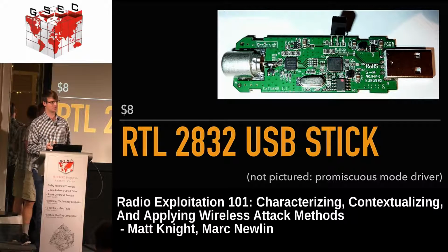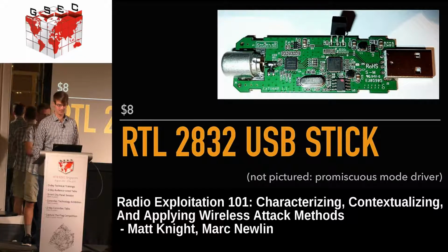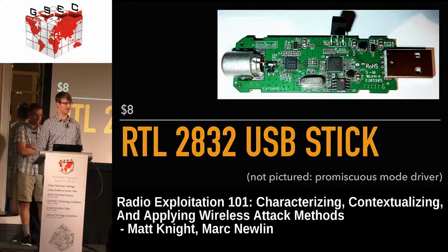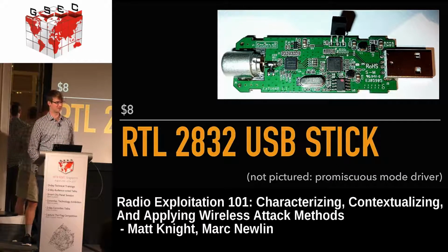This is a commercial DVB-T USB dongle. This researcher was looking at it and discovered that there was a debug mode in the RF front-end chip: if you set a register a certain way, you could bypass the demodulator and stream raw IQ information back to your host over USB. So with a promiscuous driver, you turn this thing into a poor man's software-defined radio.